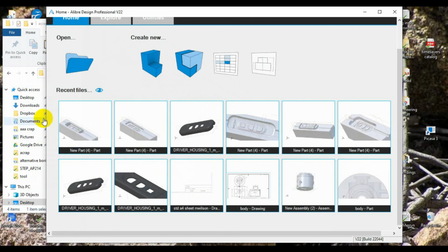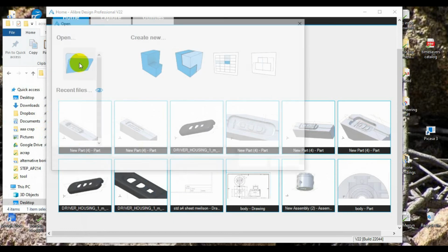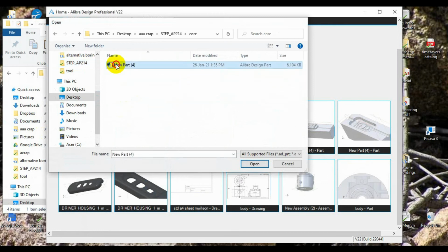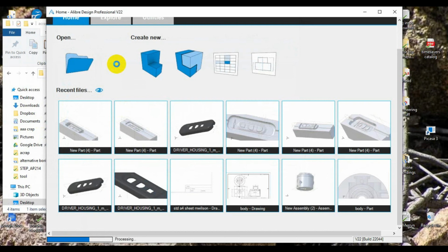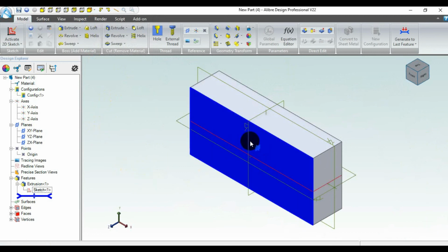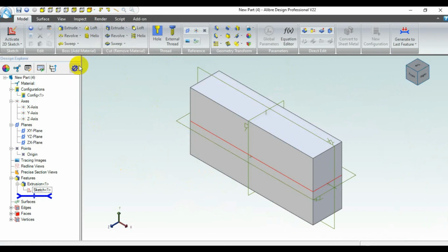Now, what I want to do is make a core. So let's just go into our measure here and we'll select the core of this particular part. This is one I prepared earlier. This new part here. And this should just be a plain block. So there's our plain block. So it's just a block. It's double the height of the existing one. So this bottom part here would be our cavity area. We now want to bring in that welded part with the cavity and Boolean subtract this from this particular block